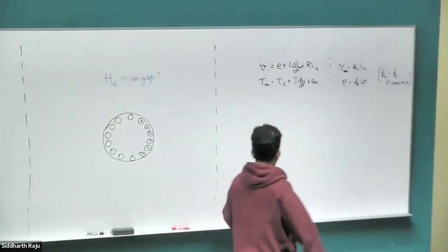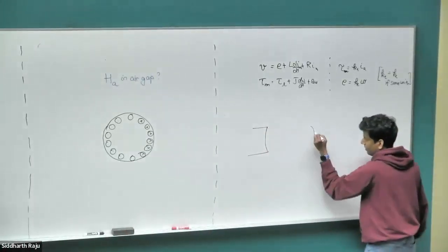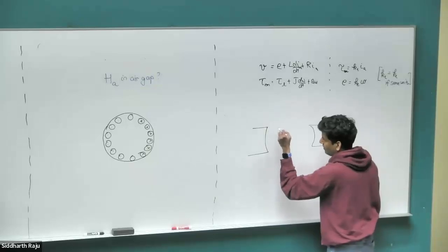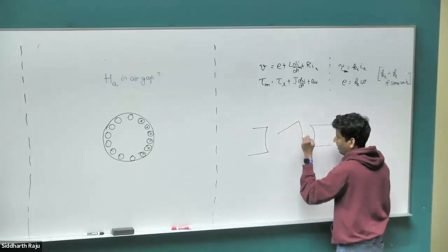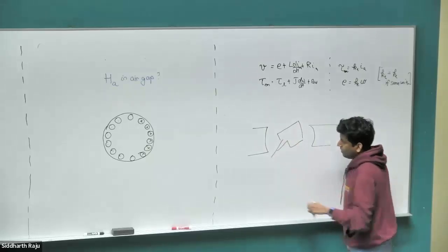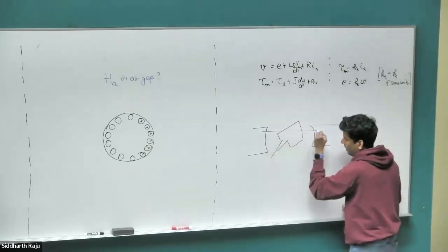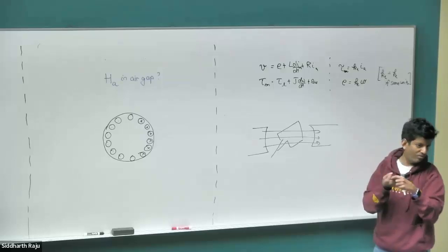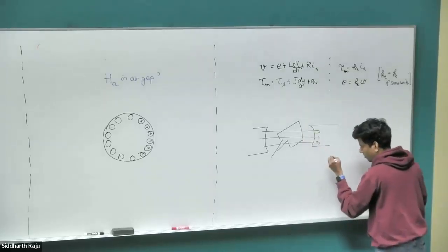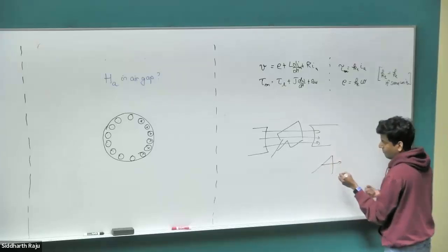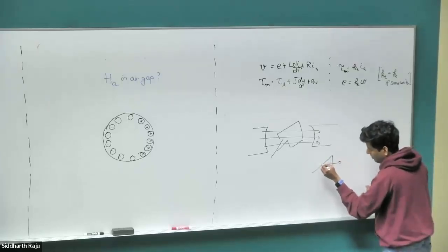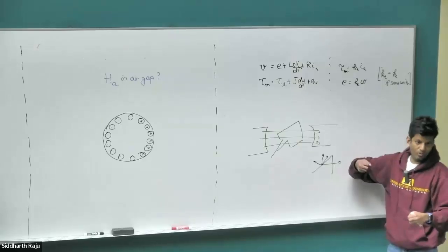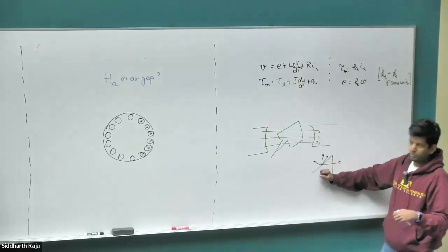So the reason we are not doing a cosine of alpha is this. We will rederive the equation for Ke and Kt in this new arrangement. But in the previous case, we were looking at a conductor coil in air, and we had magnetic field lines going straight from the north to the south. As this coil rotated, the flux through the coil was changing. If you look at this coil, we had some B field here, the current is here, and there is going to be some force produced in this direction. Only a component of the force is torque; the other component is basically pulling the coil out. And the component of force that's producing the torque we represented with the cos of alpha in tau.